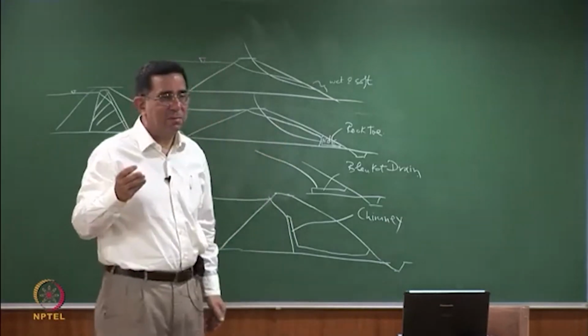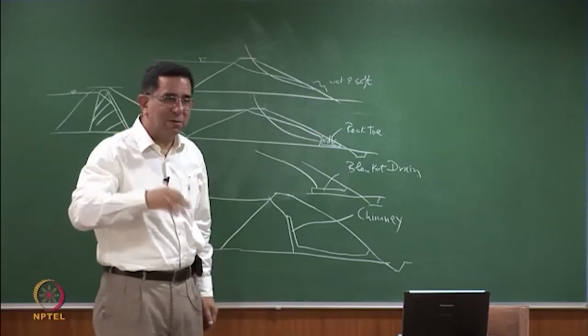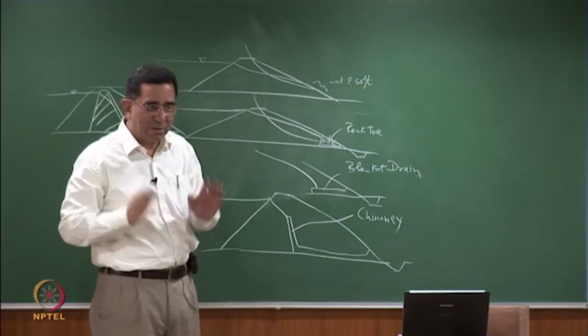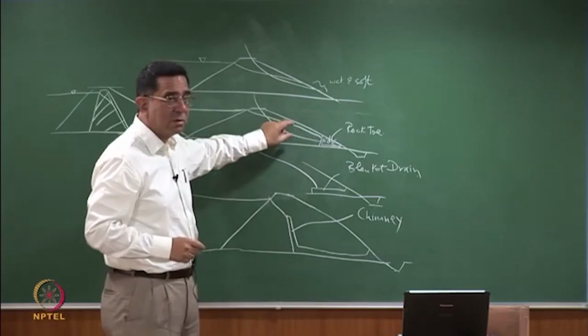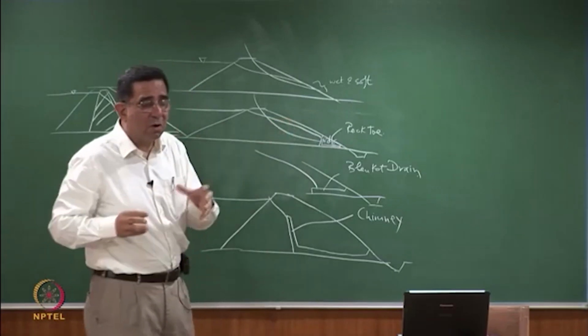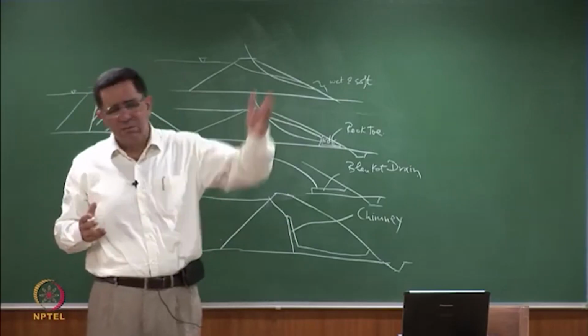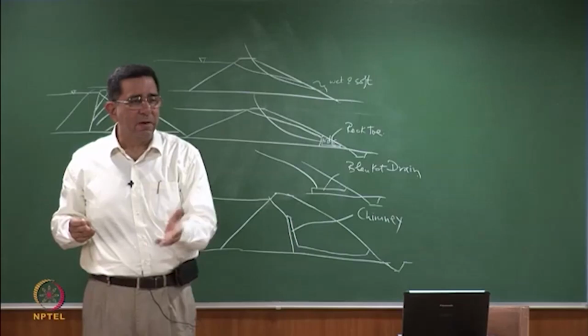factor of safety is resistance over driving, whether it's resisting moment over driving moment or resisting force over driving force, resistance over driving, right? And that's along this failure surface. When I compute the driving, what is the main contributor to the driving? The weight and the slope angle. Just make it into a simple infinite slope.